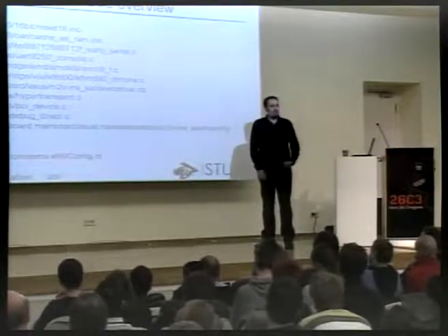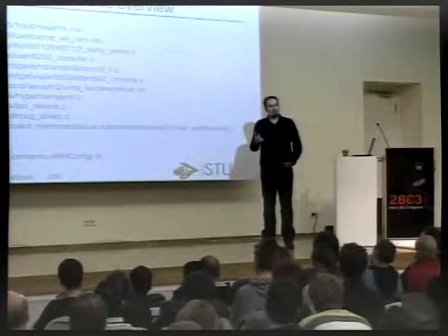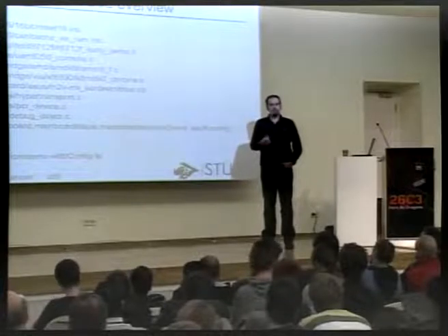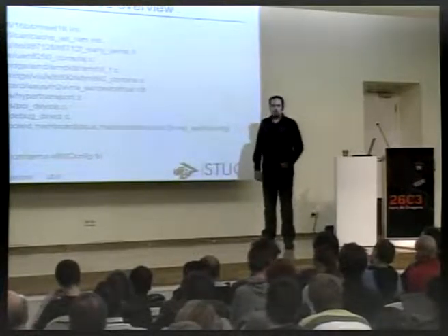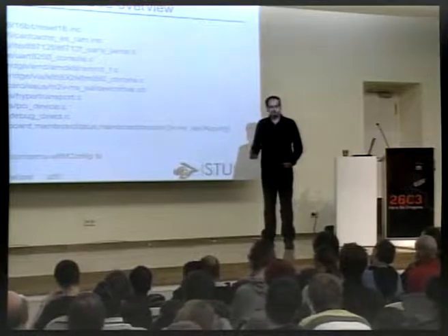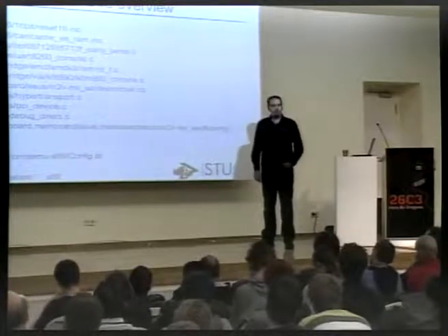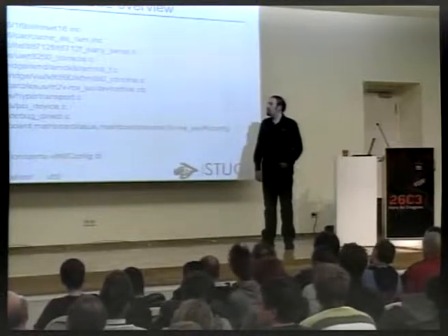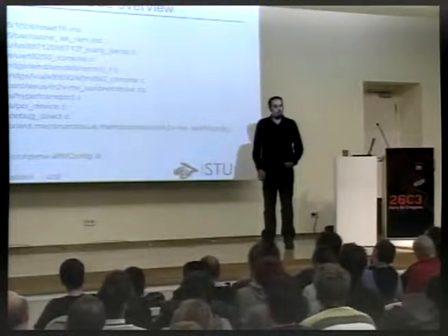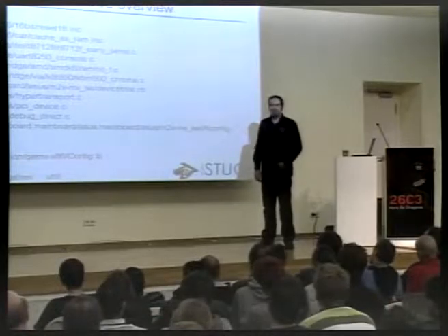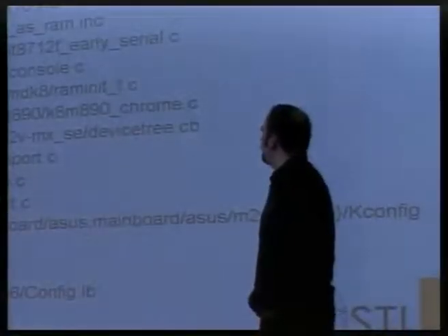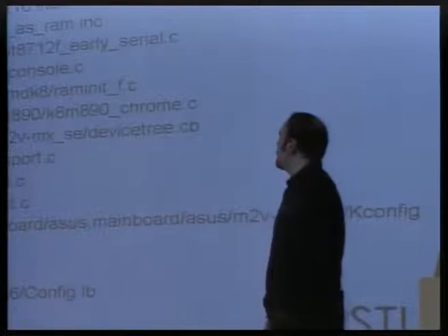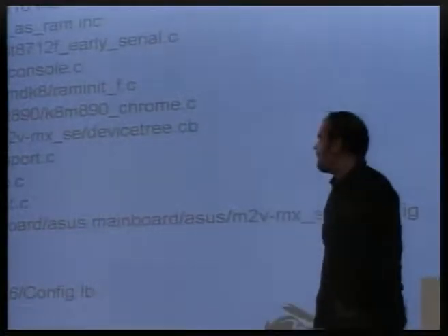And the trick is to use cache as RAM instead. So we're using part of the cache memory, which is on the CPU die, as RAM. You can set it up so that it doesn't clear and invalidate the cache, clear out the memory, or clear out the contents. And you don't have a lot of space, but you have enough to actually run C programs if they're carefully built or compiled.